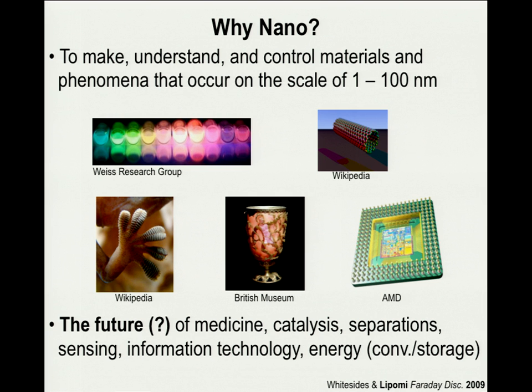But the ironic thing is that these are very much classical devices, and the effects of size confinement that we associate with nano, like quantum tunneling, are really regarded as something to be suppressed as opposed to something to be exploited, because you don't want electrons tunneling from one transistor to the next, or tunneling through the gate dielectric, for example. But this is actually what we're going to talk about today, even though we don't really consider this nanotechnology. I do, but the field generally doesn't.